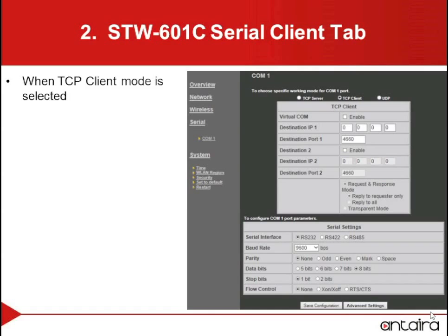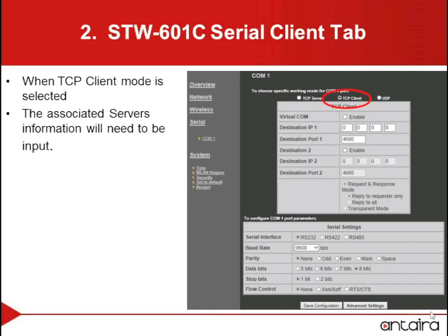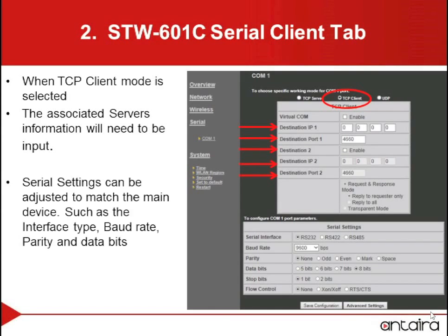Within the Serial tab, you can also select the device as a TCP client. When using it as a client, we will need to change the associated server information, as well as any serial settings. Again, any changes that are made will need to be saved to finalize them.